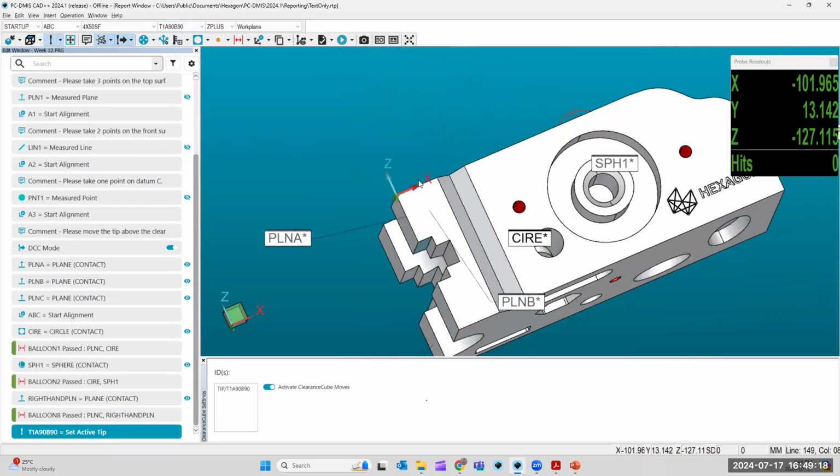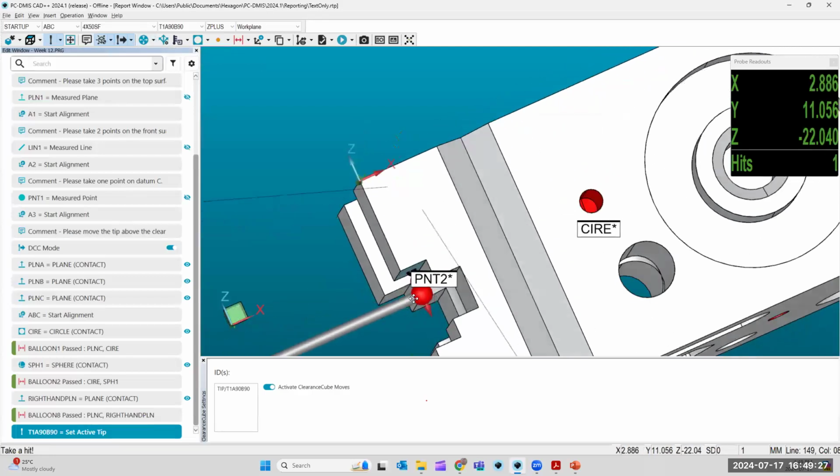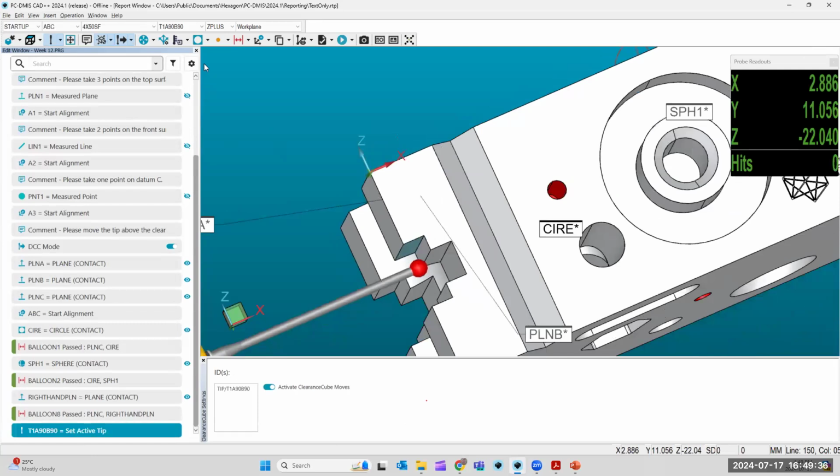And now this is what I didn't show you. We could just program this with program mode, because it's probably the easiest option. You just toggle program mode on, you click a point, and you click end. It's really quite that simple. You don't have nearly the flexibility you have if you did auto features. Here's an auto feature toolbar where you can drop down and select the exact type of auto feature you're trying to use, because the shift feature isn't as obvious how to get a point. It's actually really hard to get a point. I don't know how. So you need to go to auto feature, drop down, and I want to make a point. You could make it a plane.